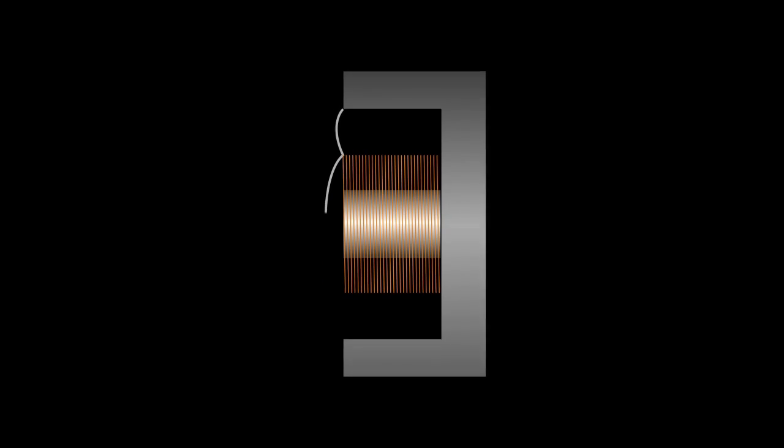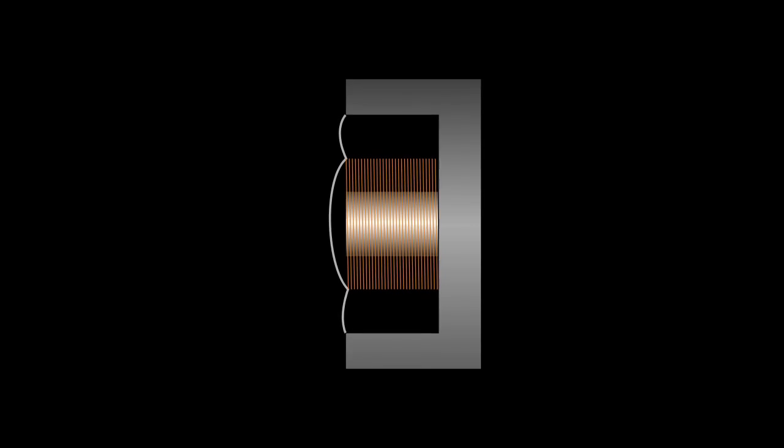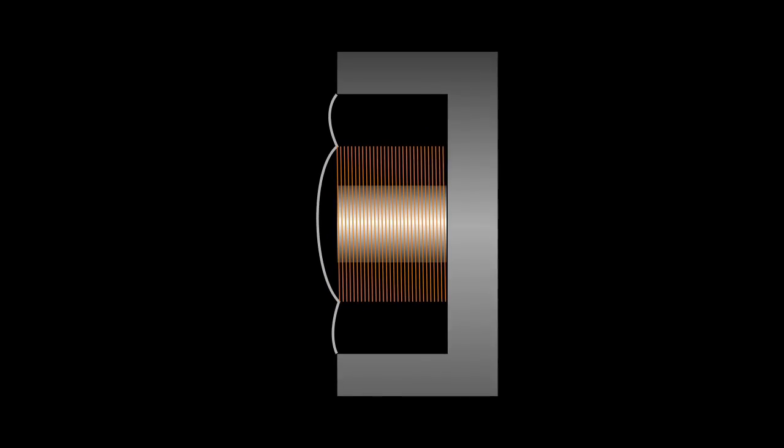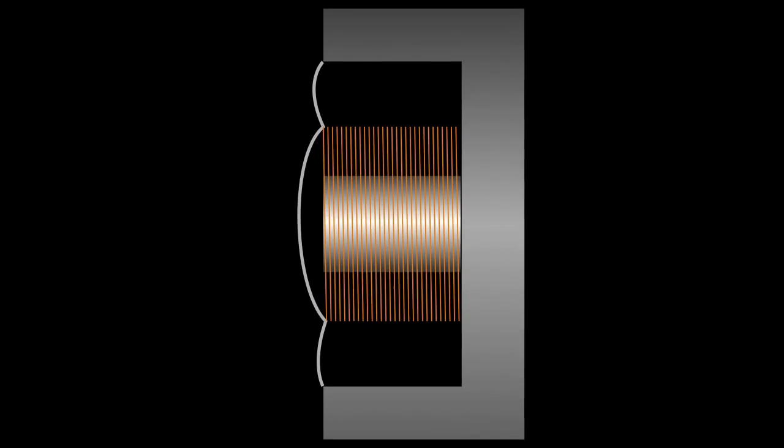There's a small movable induction coil positioned in the field of a permanent magnet, and the coil is attached to a very thin diaphragm. When the sound waves move the diaphragm, it moves the coil in the magnetic field, generating a small electric current. This electrical current is the microphone's output. Because of their construction, dynamic mics are very common for stage use, where ruggedness is important, but they're also widely used in recordings as well. Dynamic microphones in general have a more limited frequency response compared to condensers.